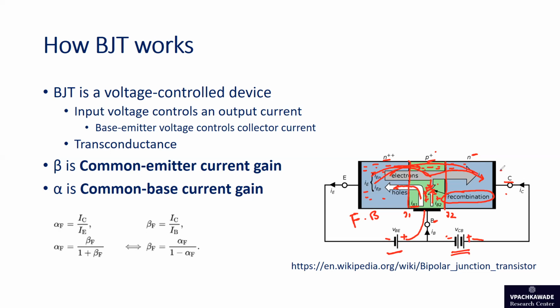This positive voltage applies the attractive force, and they collect the electrons to travel to the collector and out of the collector region and collect it to the positive terminal of the battery. This negative potential applied to the P type semiconductor will push the electrons in the P type material which have traveled from emitter towards the collector. So there is a full current going from emitter to the collector.